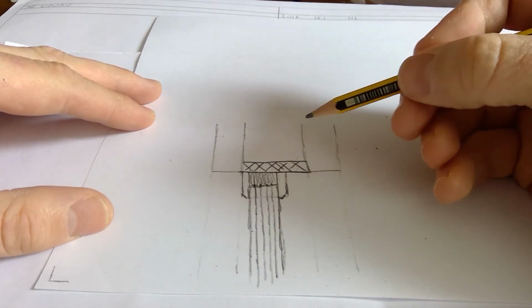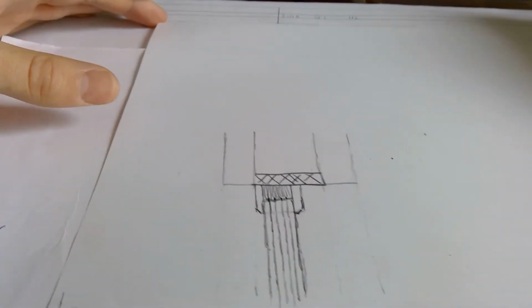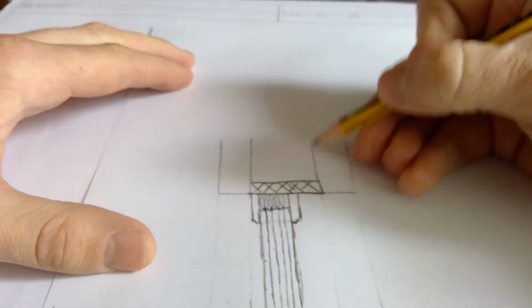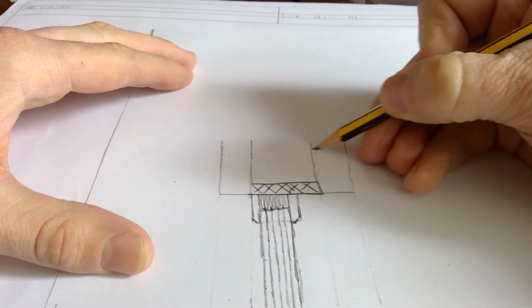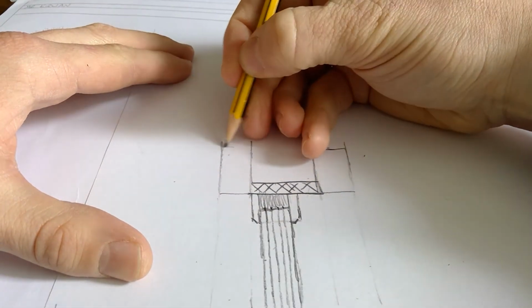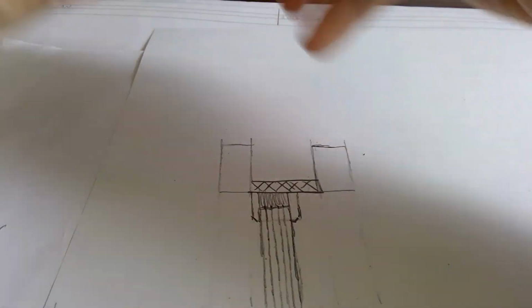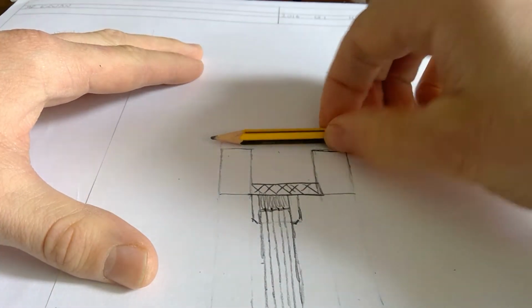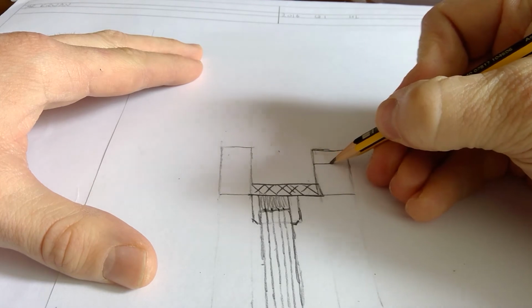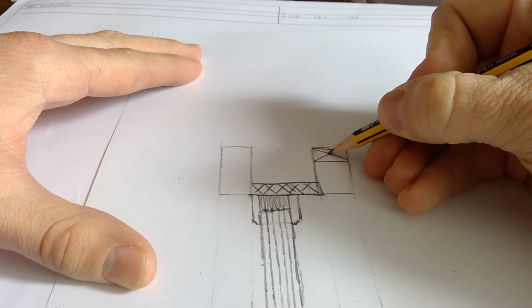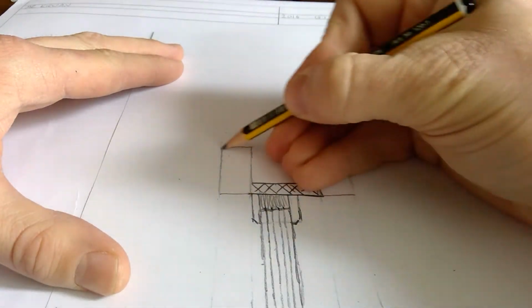Now, next we're going to go on to the eaves area of this flat roof. It's a flat roof, as we are all aware and clear. Because of space on the page, it's good just to maybe go up only one block. You know, it doesn't mention how high up to go, so usually you have an option there, but just for the sake of space, we'll go up only one block. When it comes to the eaves detail of a flat roof, the joist rests on top of the wall, and a wall plate is actually built back down into there, so they would use a smaller block, then put your wall plate on it, and that works out at an even space there.